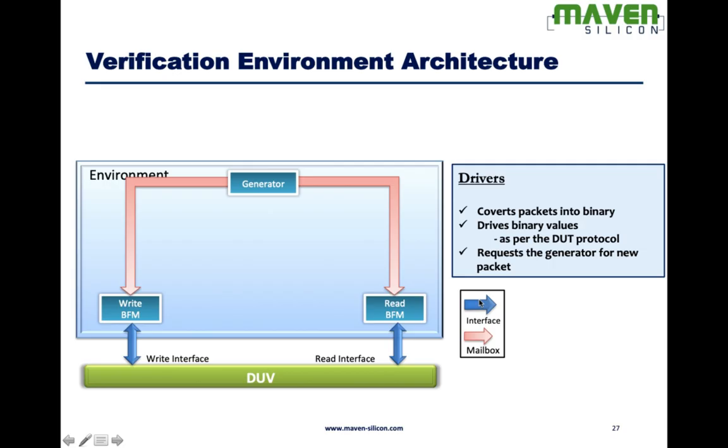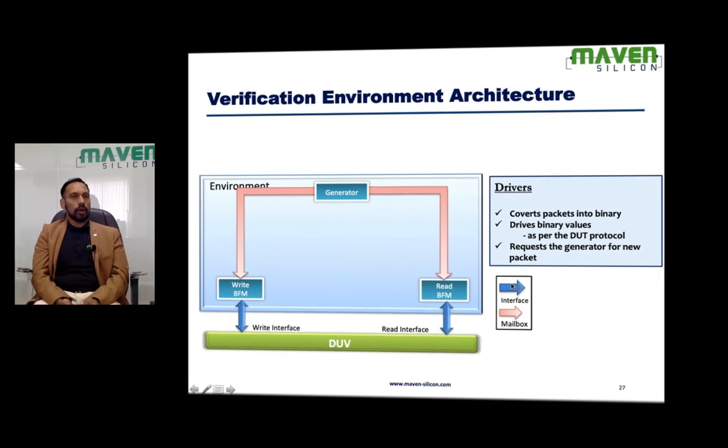Drivers convert packets into binary. Here there are two drivers. One is write driver, the other one is read driver. We also call the drivers and monitors BFM. BFM means bus function model. Any test bench component which is connected directly with interface is called a bus function model. What it means is the test bench component which runs on bus is called bus function model.